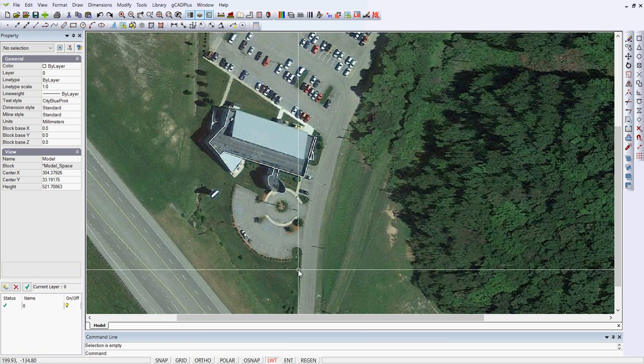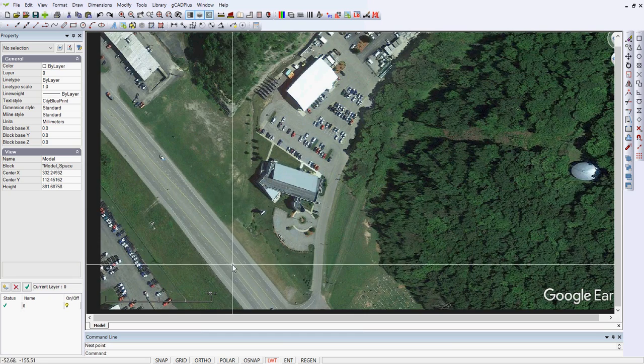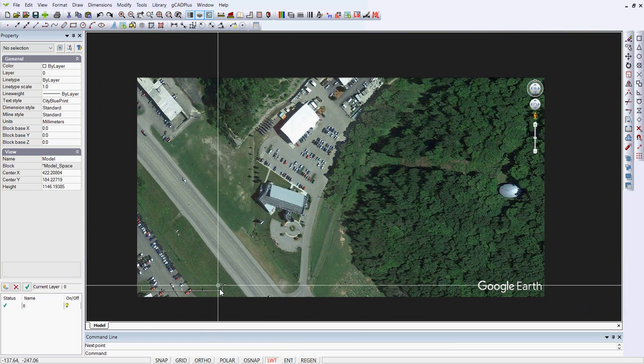Remember, we measured that driveway as 8.5 metres, so let's measure it again from one side to the other, and we get 28.29 feet. So at this point we ignore that scale. We've done our own scaling in this drawing, but it's full size in terms of feet.